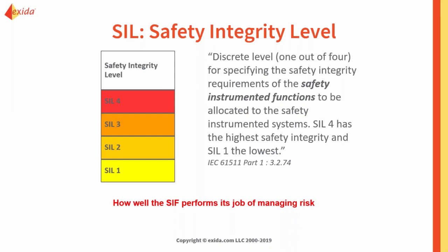It is a rating or a grade of how much risk can be removed from a system, or how well a system reducing risk does its job. Each SIL, SIL 1 through 4, is an order of magnitude higher. So SIL 1 is going to be your lowest. It doesn't have as many requirements, where SIL 4 is going to be your most restrictive, a ton of requirements going on in that. In each SIL, there becomes more and more requirements involved.